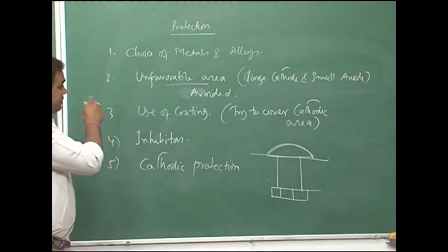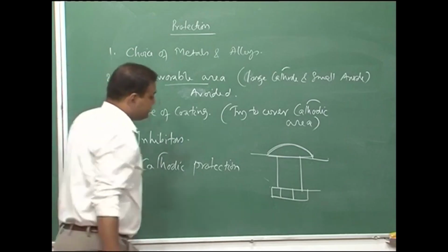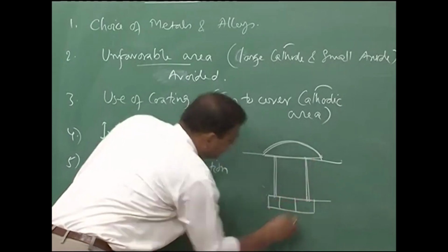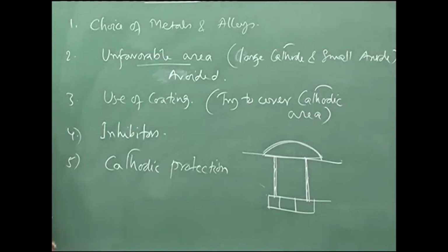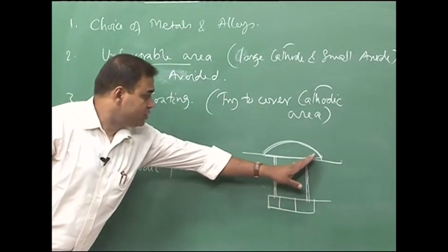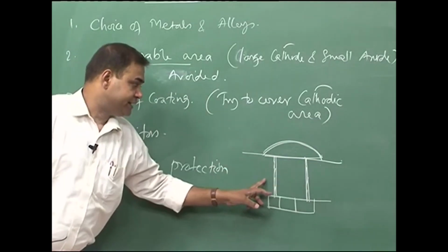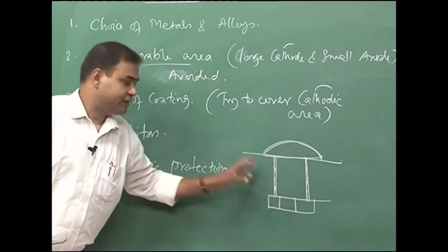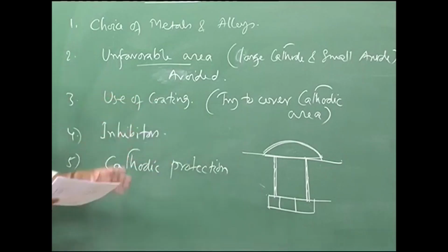We have seen that steel rivet and copper plate. In that case, one possibility is we can use some non-metallic sleeve in this zone to avoid galvanic contact. If we use a non-metallic sleeve, then we cannot have much electrical contact between this bolt and the base material, which are getting fastened.